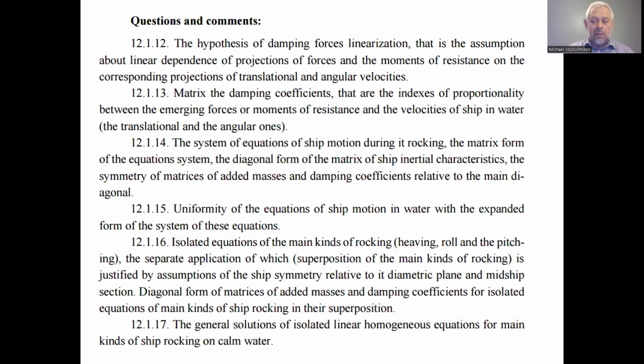So to have analytical decisions of the equations of the ship motion, we have to assume that for appropriately small velocities, the forces and the moments of resistance are proportional not to the squared velocities, but to the linear degree of the velocities.